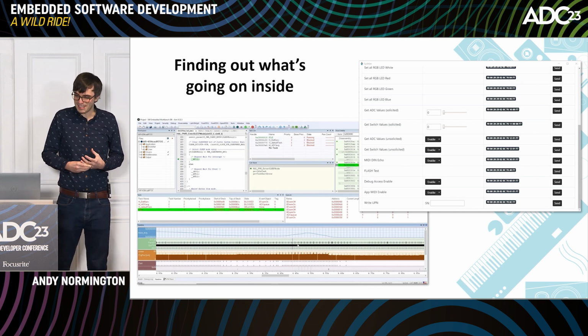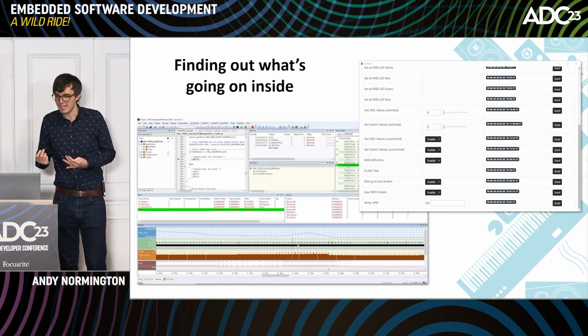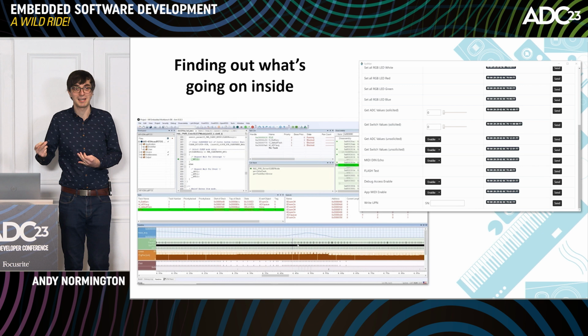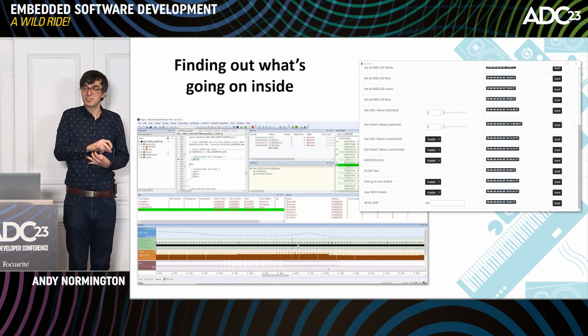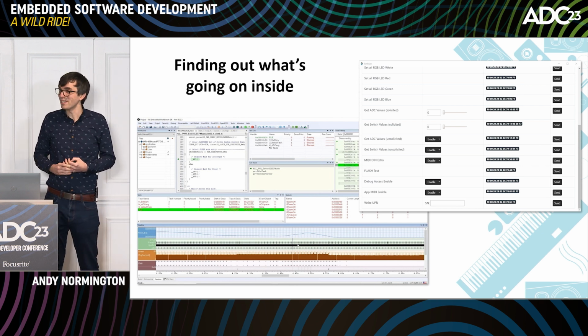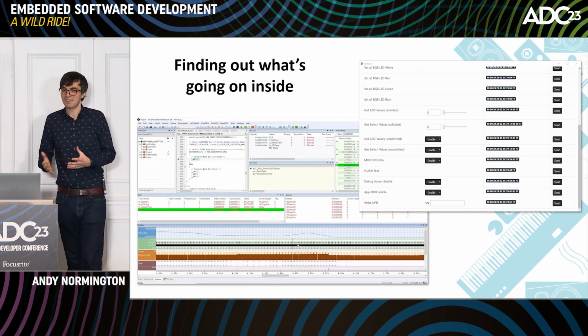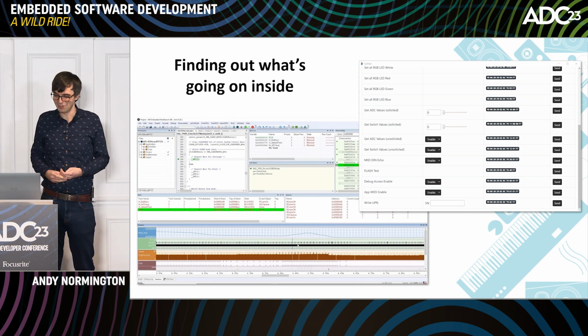Things get more physically invasive with the pin out and stuff. And you need support for each of these debug features in the silicon as well. So on a capable system, that might be OK. If we've got a low-cost Cortex-M0 microcontroller or something like that, it might just not have the silicon support for these kind of fancy debug features. We might just have to go with the toggling pins and serial debugging.